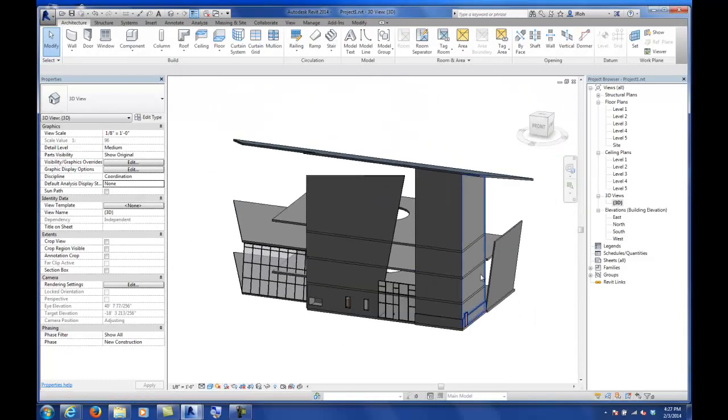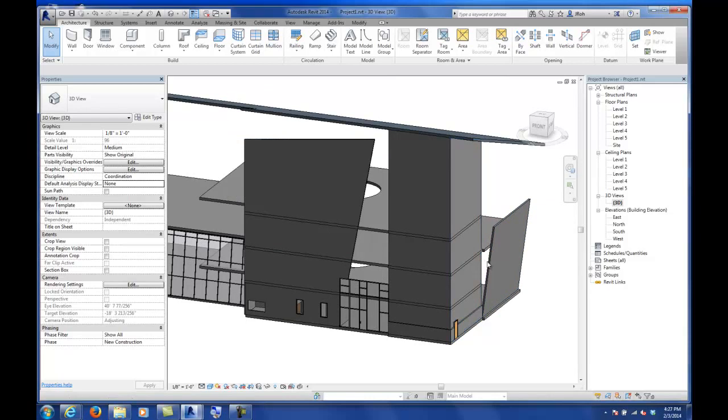That'd probably be where, if you wanted a wall to come and close this slanted portion of your particular project, you'd probably draw a wall here, make it extend all the way up, and then edit its profile so it gets trimmed back. So sometimes we have to edit the profiles of walls and things like that to start to align with our different parts and pieces.